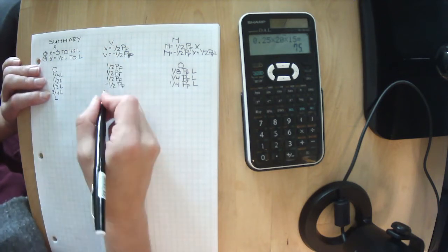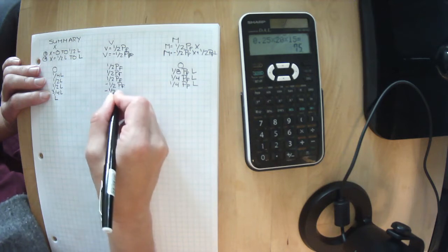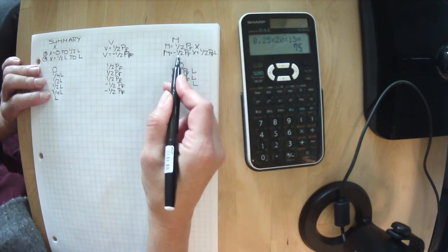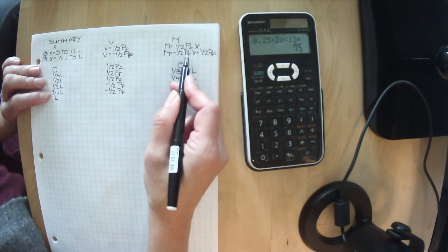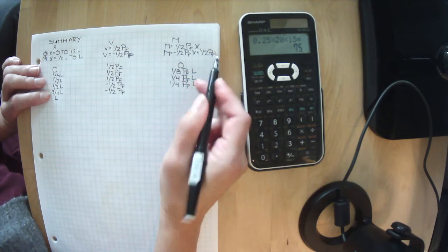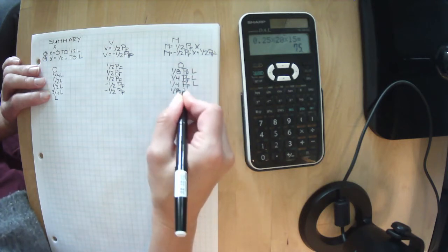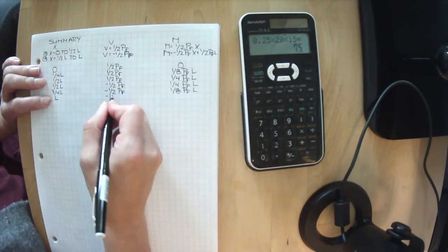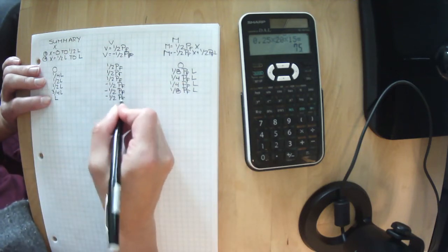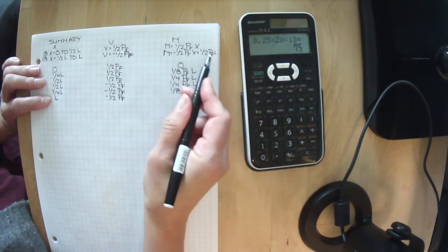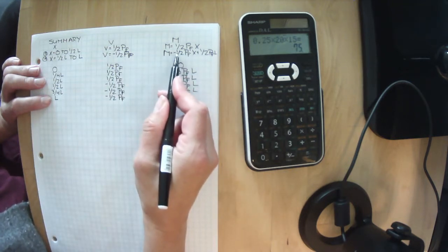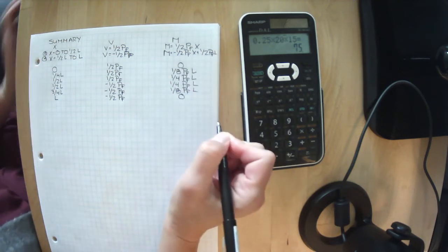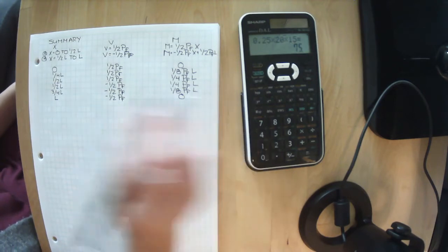Let's plug in 3/4 L. Doesn't matter, we get minus 1/2 PF. So we plug 3/4 in here, we get minus 3/8 PFL plus 1/2 PFL gives us 1/8 PFL. And then at L, minus 1/2 PF because it's not dependent on x. And then if we plug L into here, we have minus 1/2 PFL plus 1/2 PFL. We get 0.